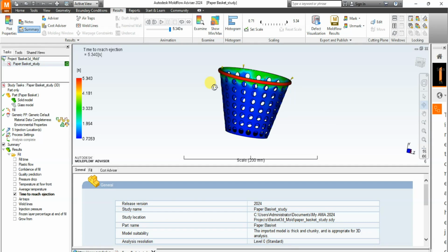Furthermore, if the resulting values for the part as a whole appear high, that's overall it's high, you can also take action to reduce the cycle time, and also reduce the mold and melt temperatures respectively. This result will help to design the cooling layout for detailed analysis of parts using cool analysis.